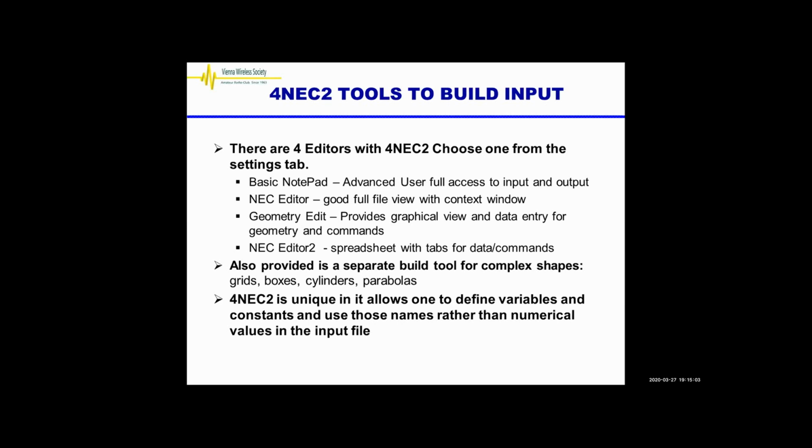So 4NEC2 actually has, and maybe if we have time at the end we'll do a demo of these, 4 different editors, and you can select which one you want to use. Quite often I use NEC Editor 2, the last one. The first one's just basically a notepad. So if you really know what you're doing with all your commands, you can just use that and enter the text. There's also a very graphical type of data entry one as well that you can use. And these are all kind of unique to 4NEC2.